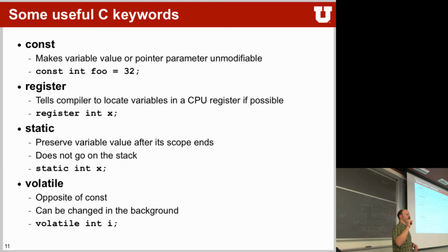Okay, you will use it a lot in the next couple labs, because basically every memory location of a peripheral is declared as volatile, because you don't know when these things change. So the compiler needs to know that variables that point into peripherals shouldn't be optimized if you try to keep reading from it.